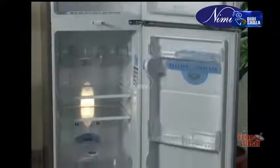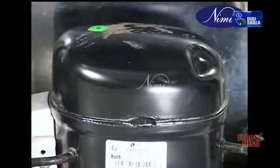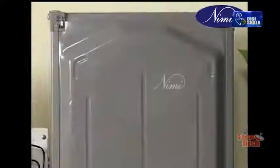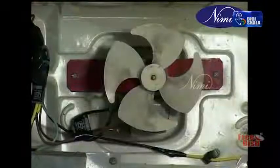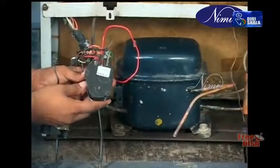Frost-free refrigerator. The operation of frost-free refrigerator systems works on the vapor compression system. The frost-free refrigerator consists of compressor, condenser, filter, capillary tube expansion device, evaporator, evaporator motor, defrosting heater, temperature control, and timer.